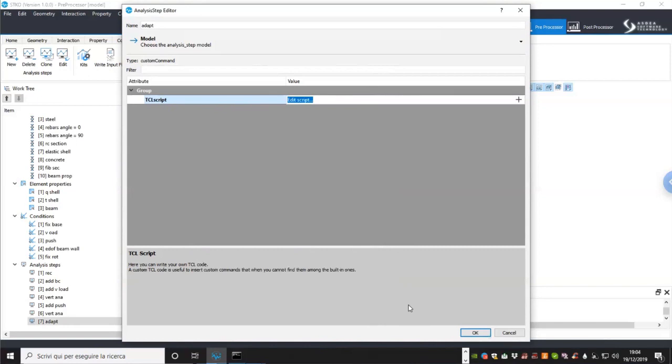Oh, yeah. So in other words, if I wanted to have a specific fiber discretization, I would have to edit the Tcl script, it sounds like. Do I understand correctly? Now, yes, but actually next week the quadtree will be ready. So in the quadtree, you can specify how many fibers you want along the X direction, along the Y direction, and how much they should refine in case of small features. Right, excellent. Be ready in a week or so.